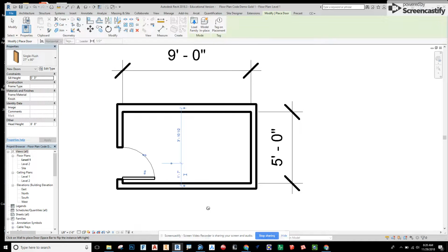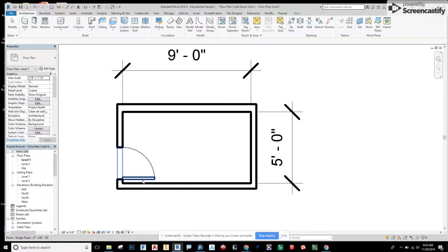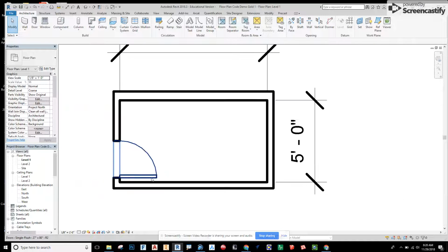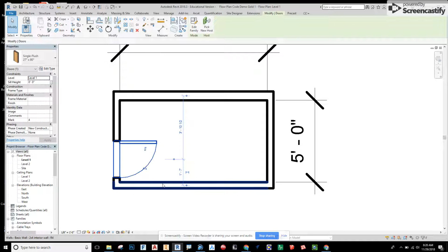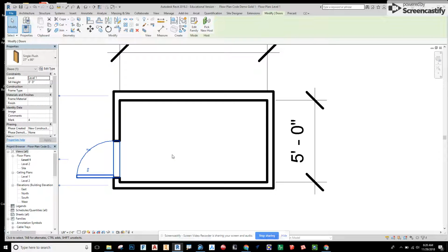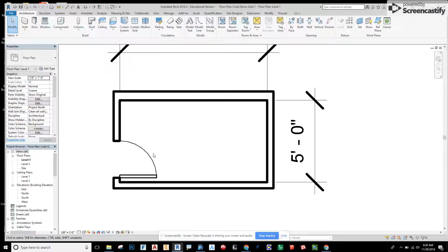Once again, when you put that door in, make sure it swings into the bathroom. Also make sure it swings against the wall, but not right up against the wall. Leave room for a door handle. If your door swung this way, you get this hallway effect as you walk in. It becomes cumbersome and in the way, especially if you have a sink here. When you're standing at the sink and you want to open the door, you have to stand around and then take a step back. So it's not really good to have your door swing into the room like that. It should swing up against a wall, preferably.